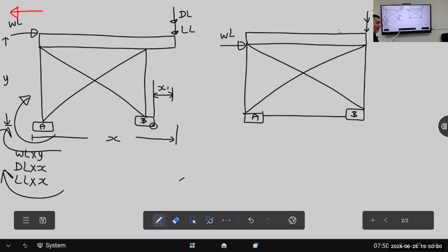Yeah, go ahead. We have a tower crane with a 7,000 pound counterweight, with a 15 foot beam extension as shown. The beam and the ball have a weight of 1,000 pounds, with the CG as shown in the figure. The tower weight is 3,000 pounds, and the footing is 6 foot by 6 foot with a weight of 20,000 pounds. Find the maximum load that the crane can lift without overturning. 2 minutes 15 seconds. Start. If two engineers solve it by calculation, I promise next Thursday after the class we will go for 5 stars.